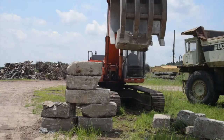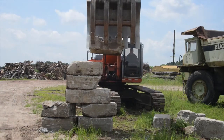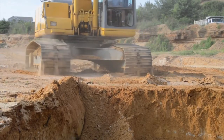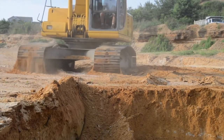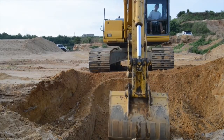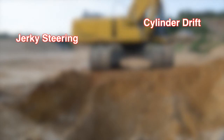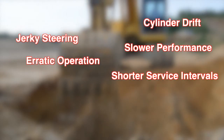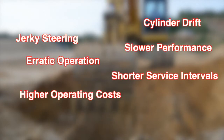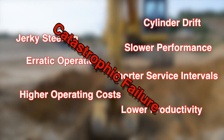Contamination can affect any machine with hydraulic capabilities. A hoe that swings too far on a backhoe loader, or one track that runs faster than the other track on a track-type tractor, can be a sign of contamination. Equipment owners and operators also see other common effects of hydraulic system contamination, including cylinder drift, jerky steering, slower performance, erratic operation, shorter service intervals, higher operating costs, lower productivity, and possible catastrophic failure.